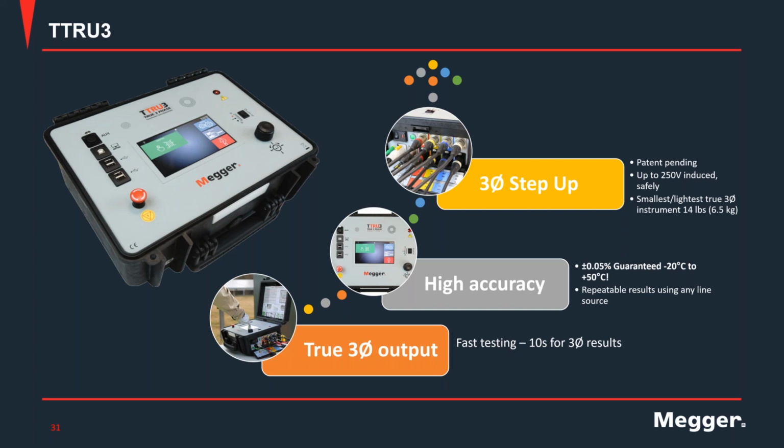The first one, and hence the name, is a true three-phase output. So the unit will be able to energize the three phases of my transformer simultaneously. Again, hence the name. Higher accuracy, plus or minus 0.5%. And really important, this very high accuracy is guaranteed in a very wide range of temperatures, from minus 20 degrees Celsius all the way to 50 degrees Celsius. That means repeatable results no matter the conditions.